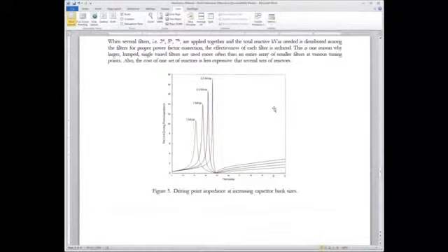What we see is, for a location at a bus remaining constant, in other words, the transformer is the same and it's not changing, the main upstream supply transformer. As we decrease our bank size, look at where the first parallel resonant point goes. So the larger your bank, the lower you push it. The smaller your bank, the higher you push it.